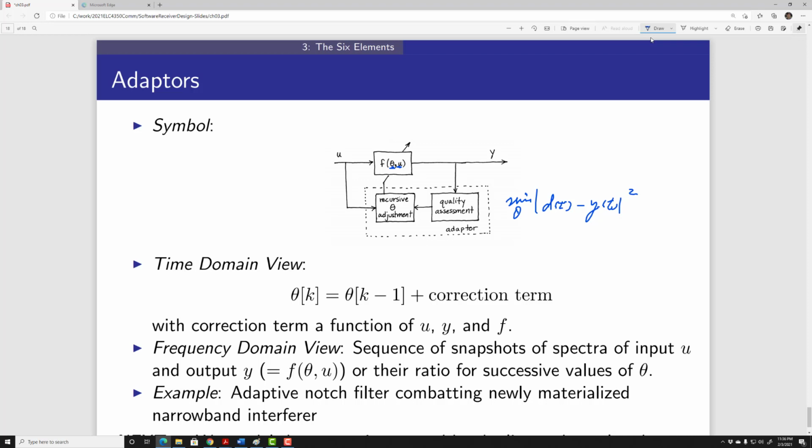For example, it can fight the carrier offset. You want the phase difference or carrier difference to approach 0. If it's not 0, if it's positive, I tune toward a negative adjustment. If the carrier offset is negative, I adjust toward a positive adjustment. Eventually, I want to make sure that the carrier offset is zeroed. The same thing can be applied to timing issues. Timing issues concern the symbol. I want to have a matched filter, exactly matched to the symbol span. If it's not, I will do some additional adjustment.